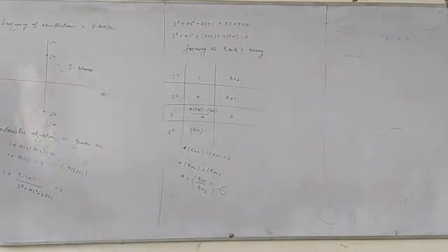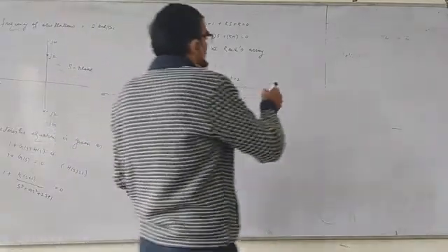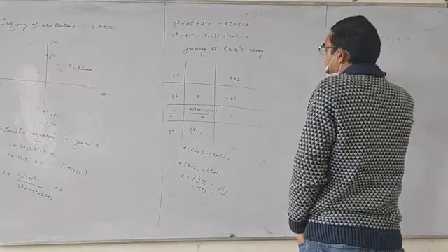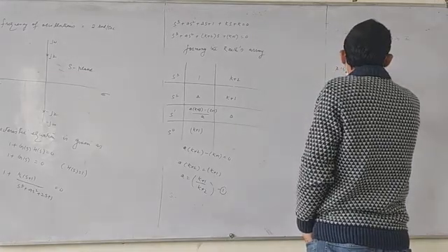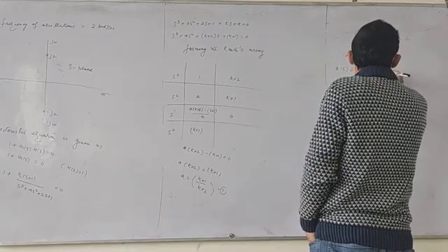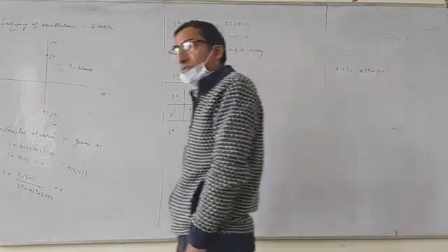That is very clear. Now where is the auxiliary equation? You can write down the auxiliary equation. The row above the row of s⁰ represents the auxiliary equation. The auxiliary equation will be given as A(s) equal to a s² plus the coefficient of this, which is (k+1), as s⁰.